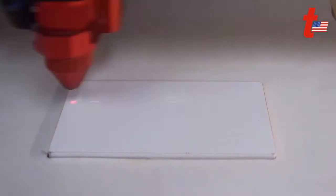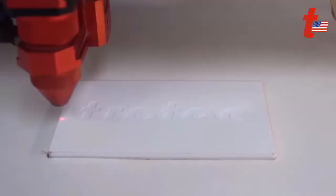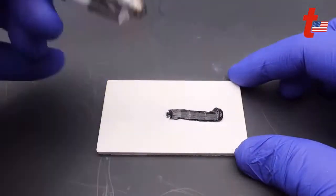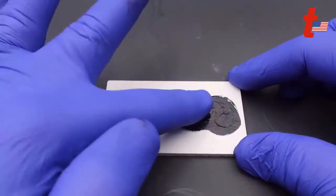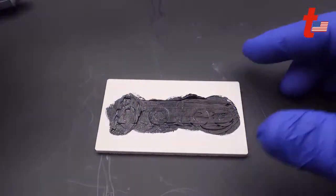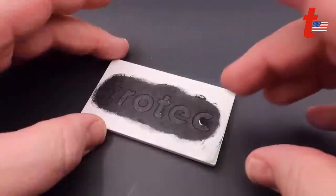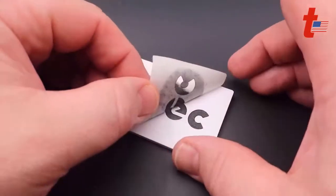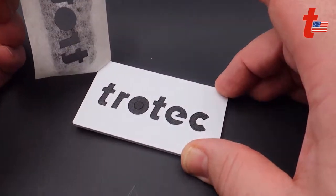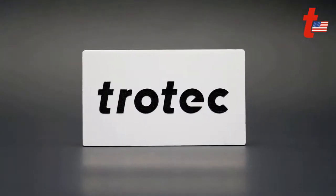Now, if you do want a little contrast, same process. This time it's pre-masked. What I did is I masked with a paper mask on the surface, and now I just engraved through it. If I want that contrast, then you can take a little bit of paint and rub that paint directly into the plastic itself with the mask still in place. So this is literally as we did it. Let it dry, and then we'll just peel this mask off, and this is going to give you that contrast. If you want that contrast in the surface, it's a pretty easy solution. I just rub it in with a glove and a finger. You can use a paintbrush, you could spray it, it really doesn't matter. But now I get that subsurface, high contrast mark.